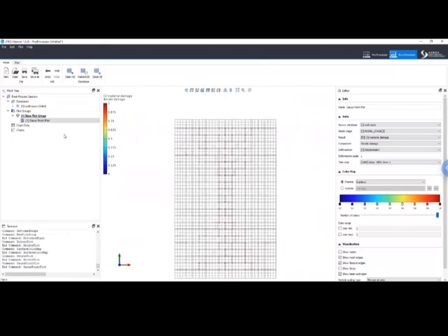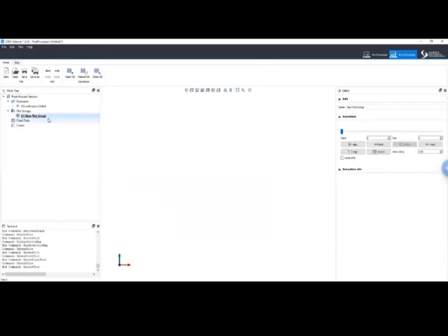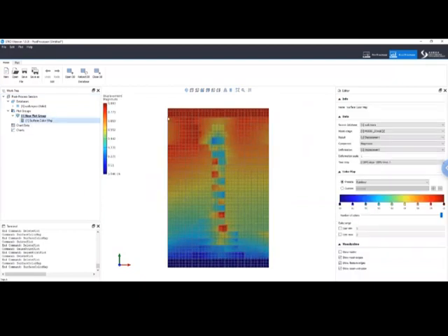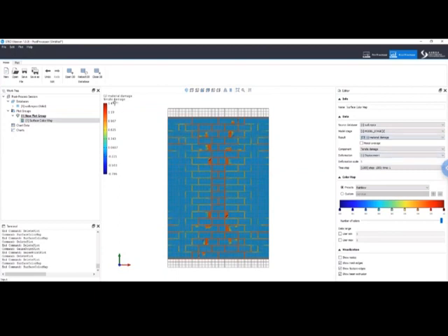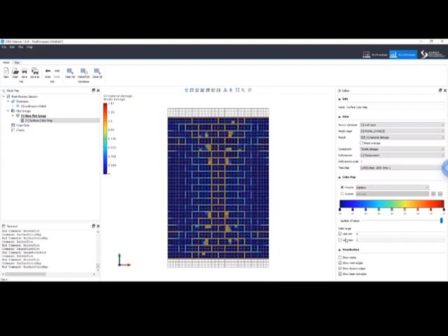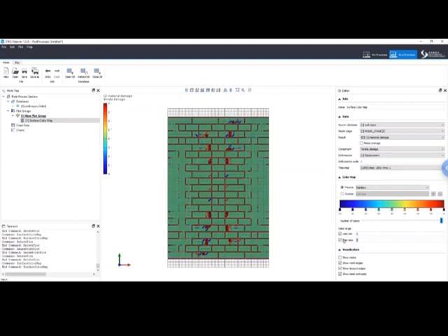But of course, visualizing the surface plot is kind of more appealing. So I go on the surface, and if you want to visualize the damage, what I typically do is I choose damage, and to avoid the fact that here I see damage which is higher than 1 or less than 0, I fix a user minimum of 0 and a user max of 1.